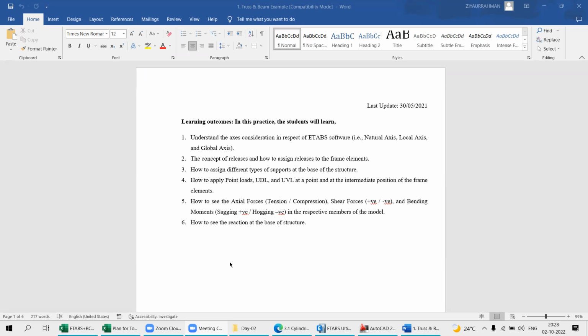The joints are assumed to be perfectly smooth, no friction. Okay. Yes. The joints are perfectly pinned or hinged. Another one also said moment transfer is not there, so both are the same. If the joint is hinged, the moment cannot transfer; only the axial force is going to be transferred.